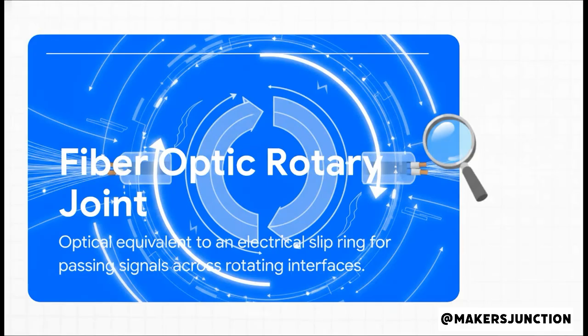The solution here is the fiber optic rotary joint, or FORJ for short. This is basically the optical equivalent to an electrical slip ring. Instead of passing current through a metal brush, a FORJ allows an optical signal, carried by light, to be transmitted right across the rotating interface. This maintains the intrinsic, super high bandwidth advantages of fiber optics end to end.